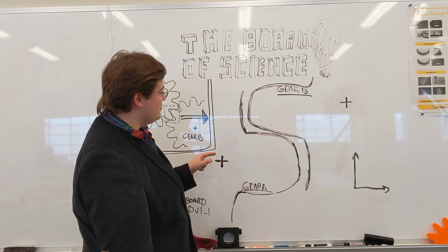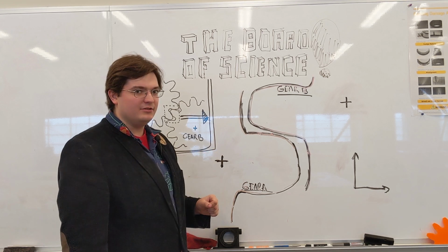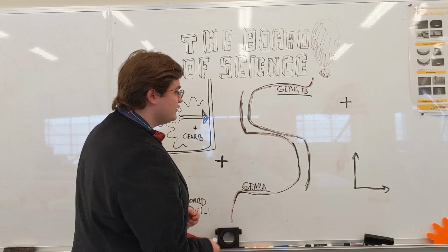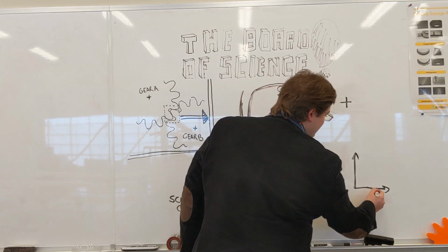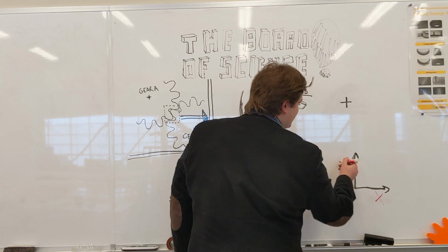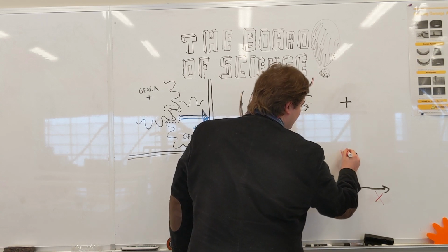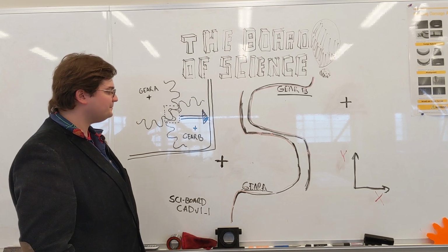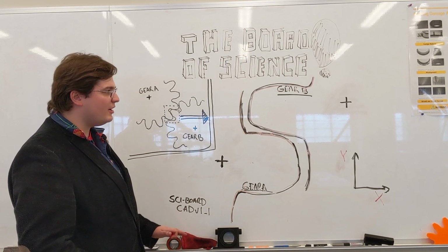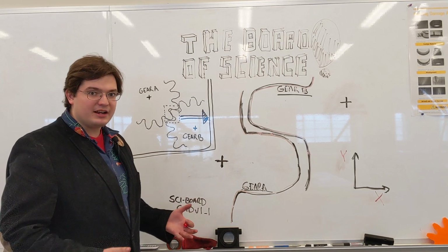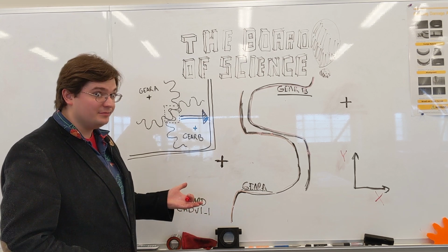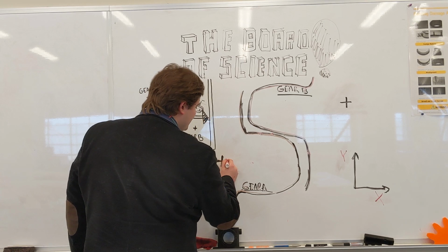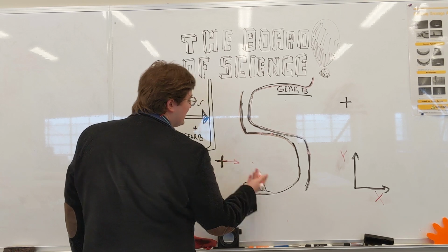So, before we begin, I would like to call out my assumed coordinate system. I'm going to call this direction X, and I'm going to call this direction Y. Just so we're on the same page here. Now looking at these gears, I'm not quite sure what's holding them up. I think we need a couple of reaction forces on each of them, don't you think? So I'm going to put in a reaction force here on gear A, at gear A's center.